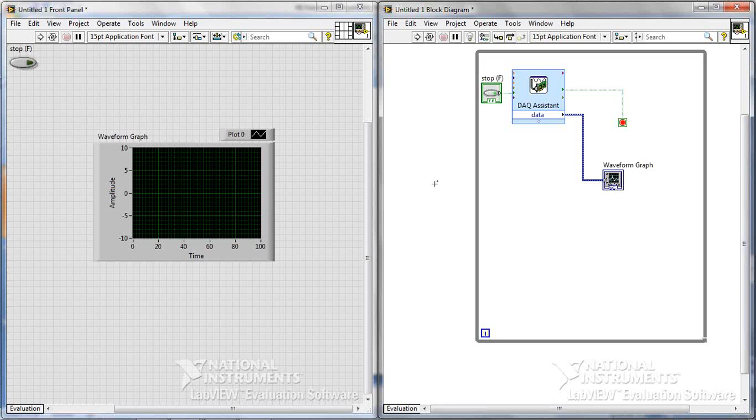Here I don't want to go for differential-ended. Like if you want to acquire, say, an op-amp, it will have two terminals, so it is a differential. Now for the sensor, I'll take only a positive, so I require only one channel. So out of two terminals, to AI 0+ I'll give my IR sensor output. To AI 0-, I'll make it ground, since I want it in single-ended mode.